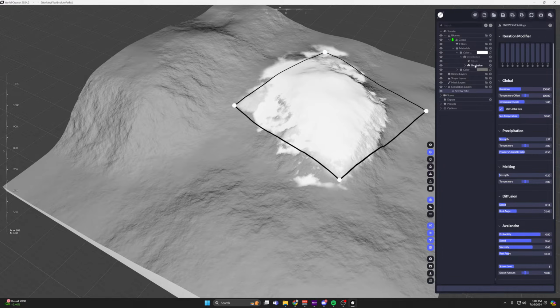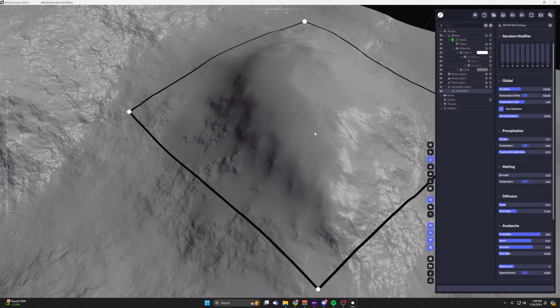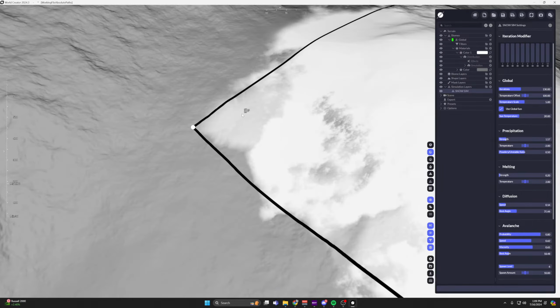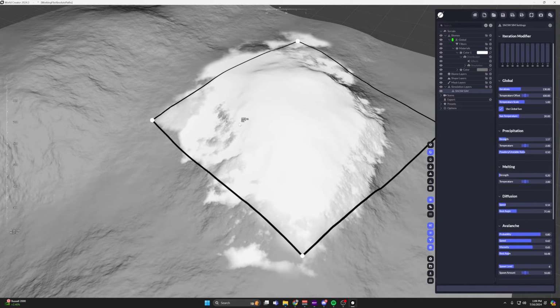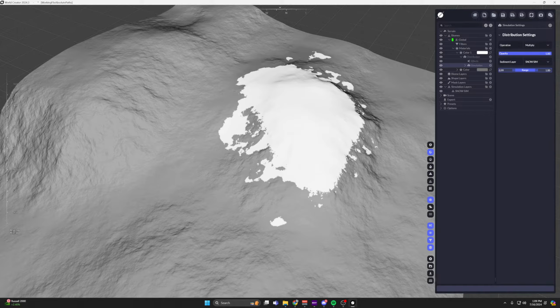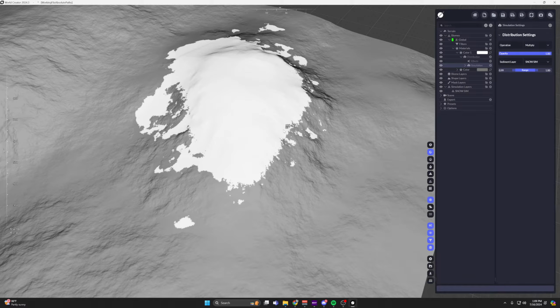Oh, also, if you want to see this simulation not in the matcap view, because like I said, it's going to make it really colorized, in the fast texture render you can see some of this snow is kind of bleeding off the edge a little bit. If this is confusing and you want to really see what the simulation is doing for you, in the materials where you have the snow under the simulation layer, you have this range, so you can control the range at which the simulation or the material is painting on the sim. If you take this lower value and put it at like 0.99, you can really see the boundary of where the simulation is, sort of one-to-one.